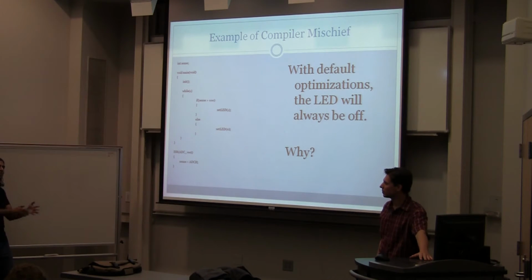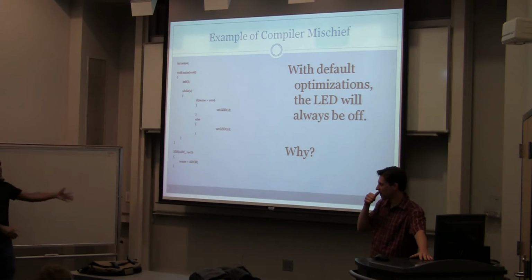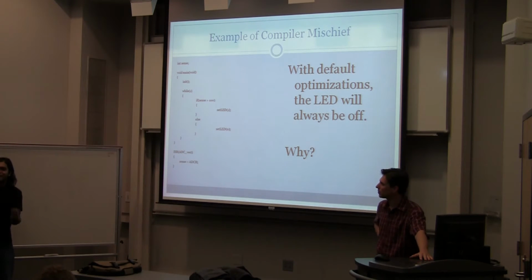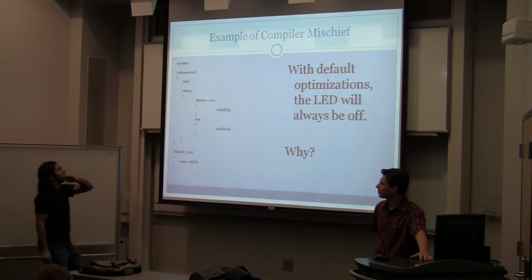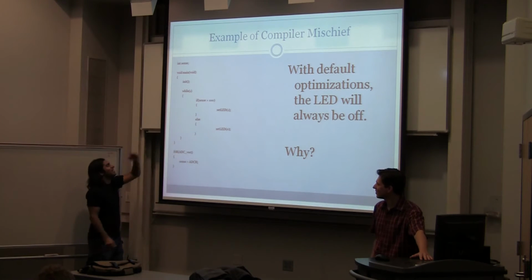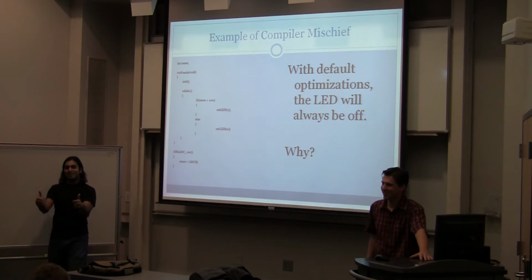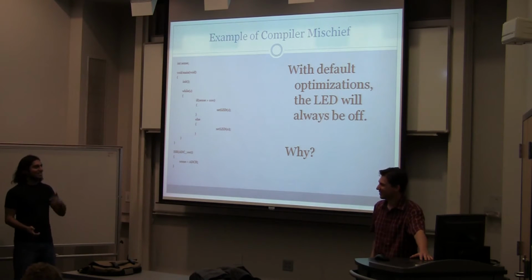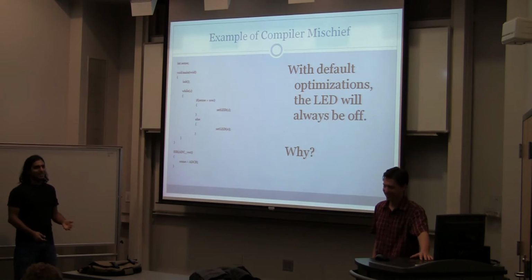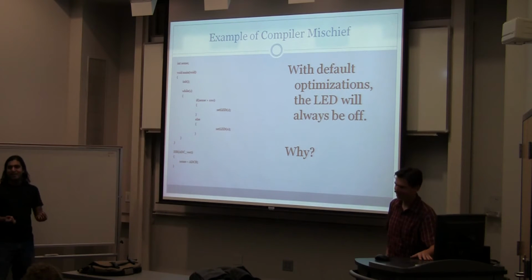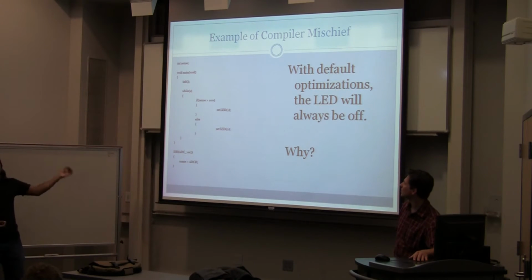So if you don't report stuff like that to the compiler, it can optimize out things because it thinks it's being smart. It's thinking, well, I just saved you like 1 billion cycles because now you don't have to do this while loop at all. Like I've totally solved this problem, you're good to go. And then in reality, what it's done is just completely wrecked what you were trying to do. And so basically, it's just a matter of telling the compiler what you actually want.